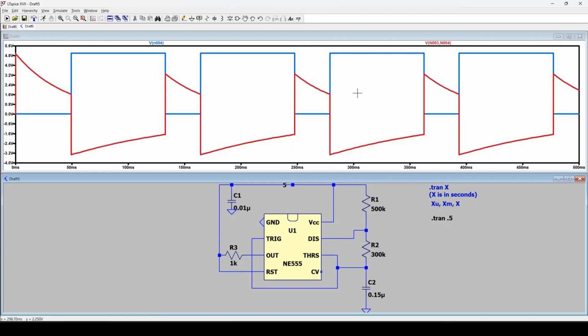And as you can see, I'm now taking the differential. I'm now taking a voltage measurement of the capacitor, of the voltage across the capacitor, relative to the output node of this chip. So overall, the principles of the OP analysis and how you can take voltage measurements stay the same. The syntax for transient simulation is different, but you can also view currents and voltages just the same. So that's how you view time varying circuits.